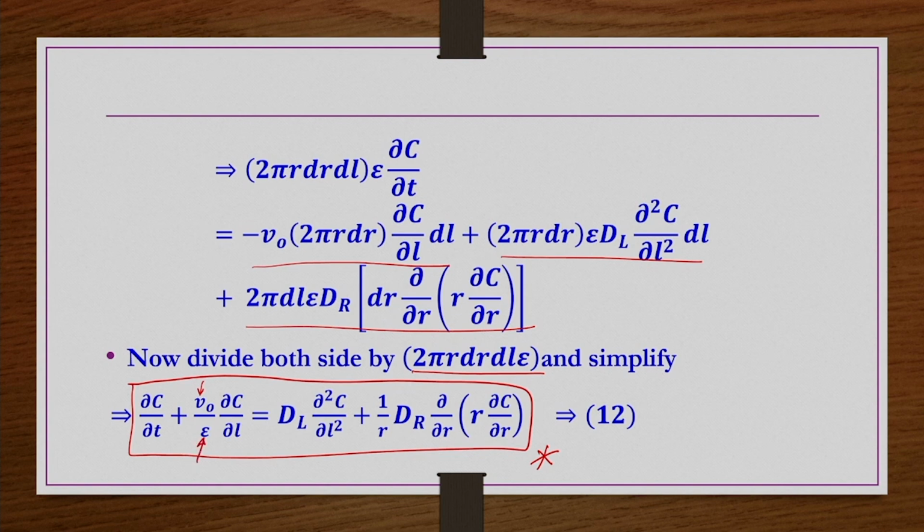You also know the epsilon voidage of the bed that you have made for your real life situation. So, if you wanted to find out the change in concentration with respect to space and time, that is C as a function of R, L and T, then what should you have? You should also have the information of dl and dr, only then can you use this equation to know the change in concentration because of the dispersion. Otherwise, this equation is as useless as nothing has been done.